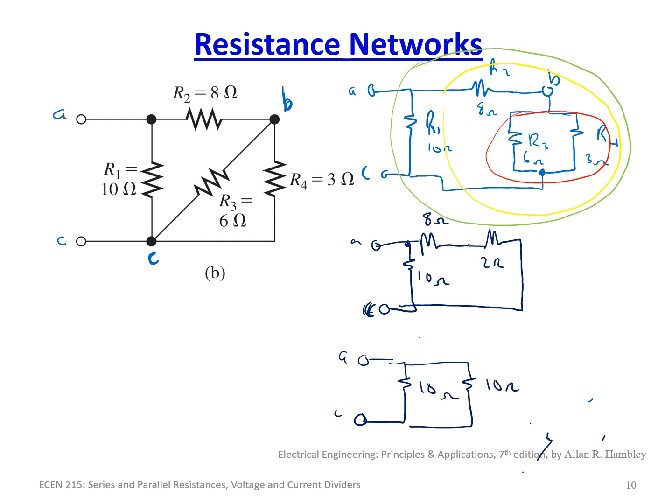Which is what? Well, just simply put, when you have two of the same thing in combination, so I have a 10 ohm and a 10 ohm in parallel, it is just simply 10 divided by 2. So if I have 5 and 5, it'd be 5 over 2. If it's two 20s in parallel, it'll be 10 ohms, etc. So this immediately becomes one resistor that is 5 ohms. And that's the answer.